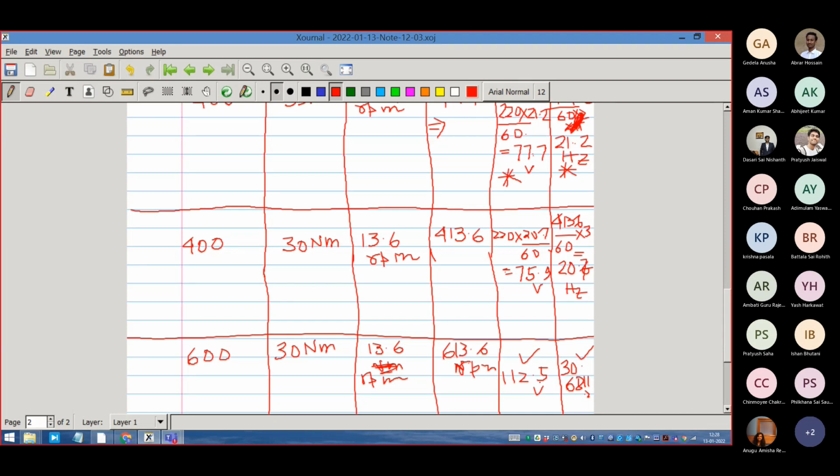You take any speed. This is the method. This is where the machine has to ultimately land up to. This is if I need to give this kind of voltages to the terminals, and the machine will eventually respond by reaching a steady state rotor speed of 600 RPM and developing a 60 Newton meter torque at the shaft, which the load demands.